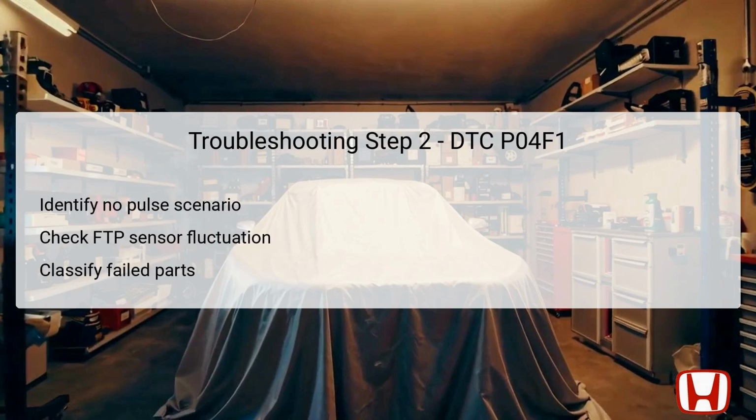In the second troubleshooting step, focus on understanding the no-pulse scenario clearly. If the technician determines that there is no pulse from the EVAP canister purge valve, this points towards either an absence of purging flow or a malfunction where the purge valve might be stuck open.